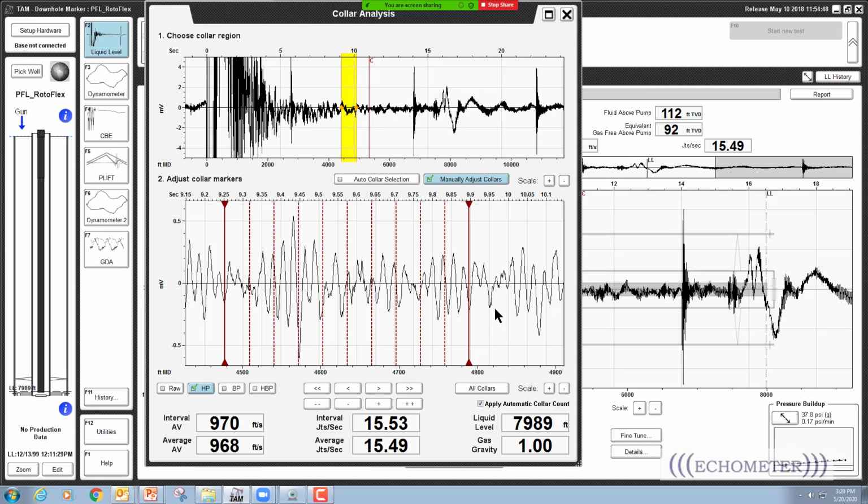Shooting down gas lift wells while they're still injecting, I typically prefer to shut the injection gas off to minimize the noise. But sometimes you've got a compressor on location, and if you shut it in, you're going to knock the compressor offline and have to get someone out there to start it back up. But if you take a fluid level shot while it's still injecting gas, the acoustic velocity as it's traveling down the well is going to be faster than normal, right? Due to the injection gas. And then conversely, on the way back up the hole, where the wave is coming up against injection gas, it's going to slow down. But in the balance, does that all net out? Is it going to be the normal acoustic velocity you would get if you shut the injection gas off?